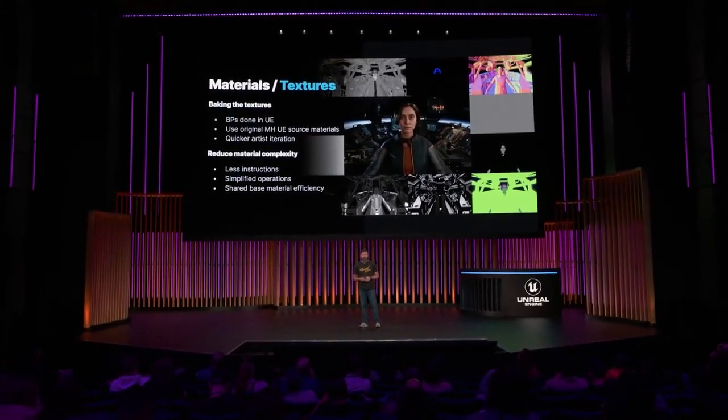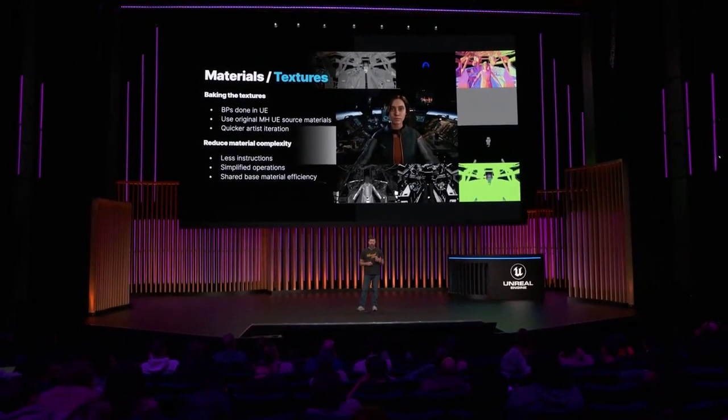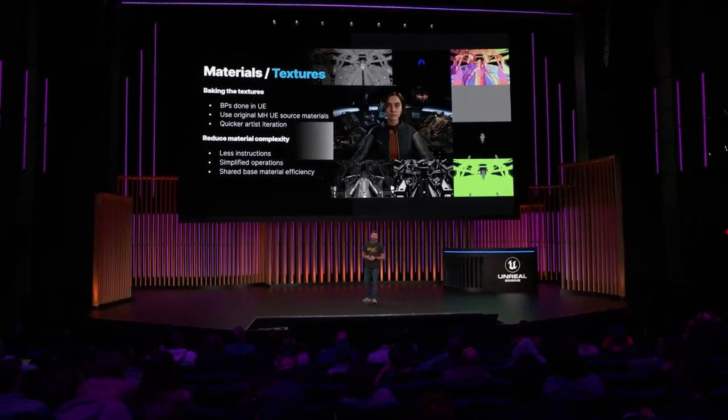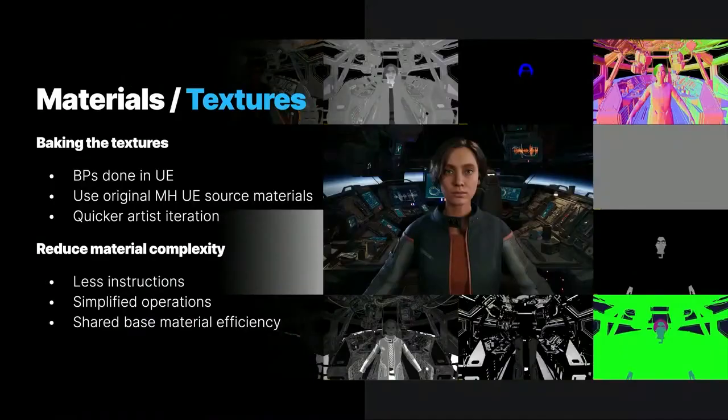The high-quality MetaHuman has animated wrinkle map and face color maps. The medium version removes those animated maps, and the low has subsurface turned off with baked AO to bring back some fidelity. In the lower LODs, we also used baked grooms to save performance where it made sense, like eyebrows and some mustaches. For face materials, we ended up with 3 different material LOD versions. Each material has its own resolution setting, and is only used for the corresponding LOD level.